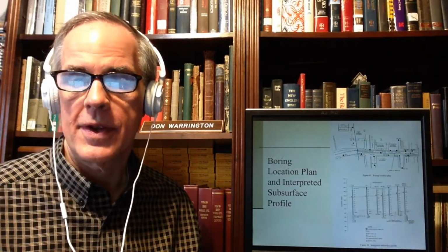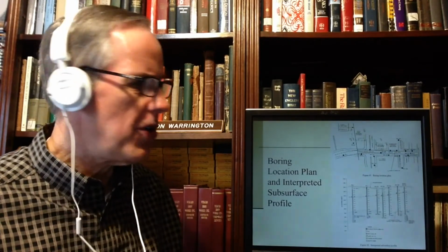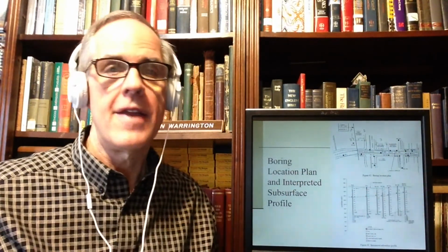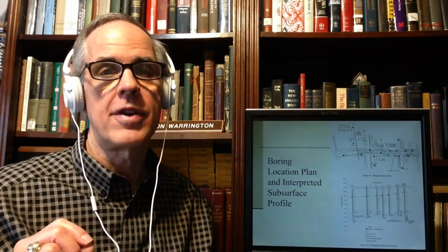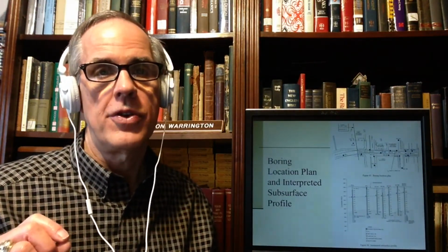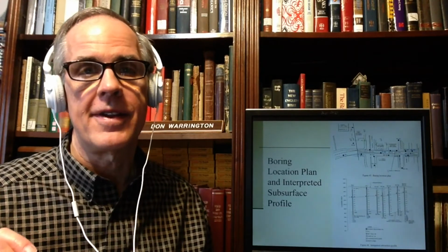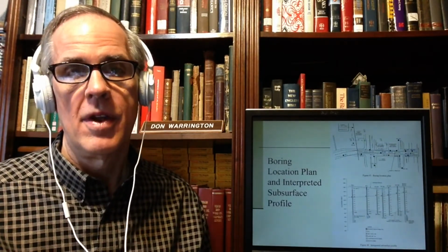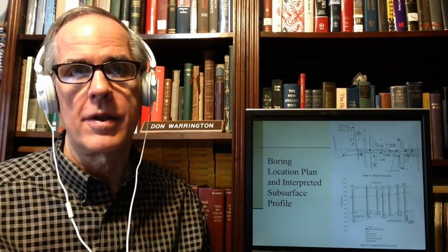Another thing is the interpreted subsoil. Usually if you look at this, some of the boring logs will kind of line up in a row. And you can take that as a cross section and you can use it. In fact, you're seeing some of your newer geotechnical packages for generating these things, and virtually all of them are now generated by computer. It's the rare boring log that's done by hand anymore.